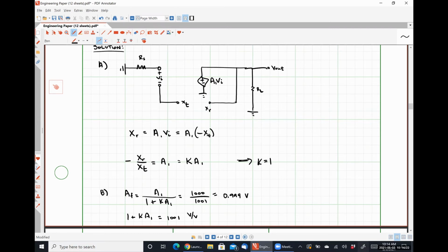So like in an example that I work in circuits 2, we see that for an input resistance of 100K or 150 kilo ohms or something like that, we wind up seeing an input resistance from the perspective of the input voltage source of somewhere around 5 mega ohms. And similarly for an output resistance having a value of 25 ohms, from the perspective of the output terminals of the op amp, it actually looks like less than a single ohm. And it's this feedback scaling that causes that to occur.